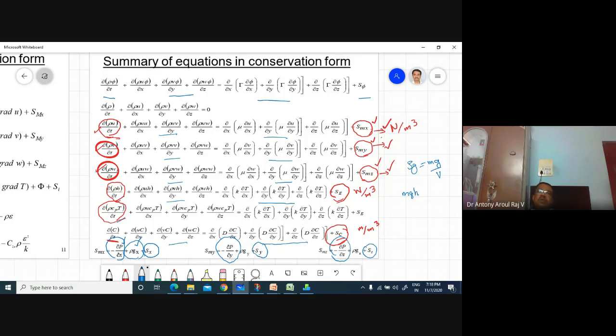What's the reason? It is like you are storing the energy. Whenever you want, you open the tank, you are getting that. How is this flow created in the tap? The pumping energy is stored in the tank, in the form of potential energy, mgh. Or think about water available in the mountain, it has energy. Likewise in the house, we are pumping the water to the overhead tank. So that is mgh.